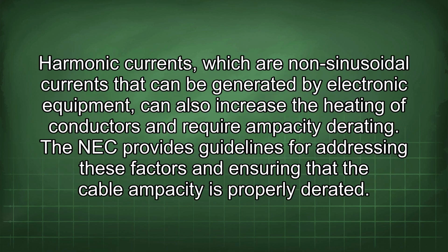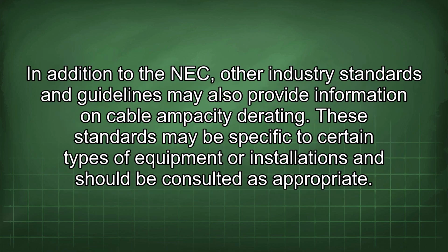Harmonic currents, which are non-sinusoidal currents that can be generated by electronic equipment, can also increase the heating of conductors and require ampacity derating. The NEC provides guidelines for addressing these factors and ensuring that the cable ampacity is properly derated. In addition to the NEC, other industry standards and guidelines may also provide information on cable ampacity derating. These standards may be specific to certain types of equipment or installations and should be consulted as appropriate.